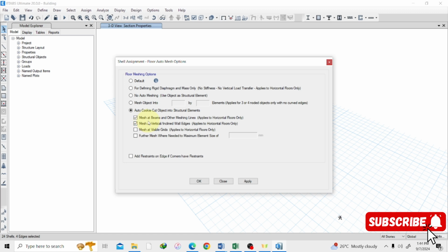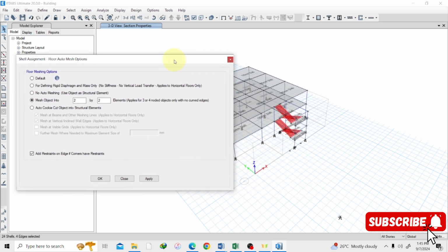So with this one, we have mesh at beams and other meshing lines. You are giving them some rules the meshing is supposed to follow. There is also mesh at vertical or inclined wall edge. You can choose to use these, but I really don't like the option. So I'm just going to mesh objects into 2 by 2. Also I'm going to check this box because I want to add restraint on edges if corners have restraints. So that's it. Once I'm done, with my slab and everything selected, I'm going to apply this.